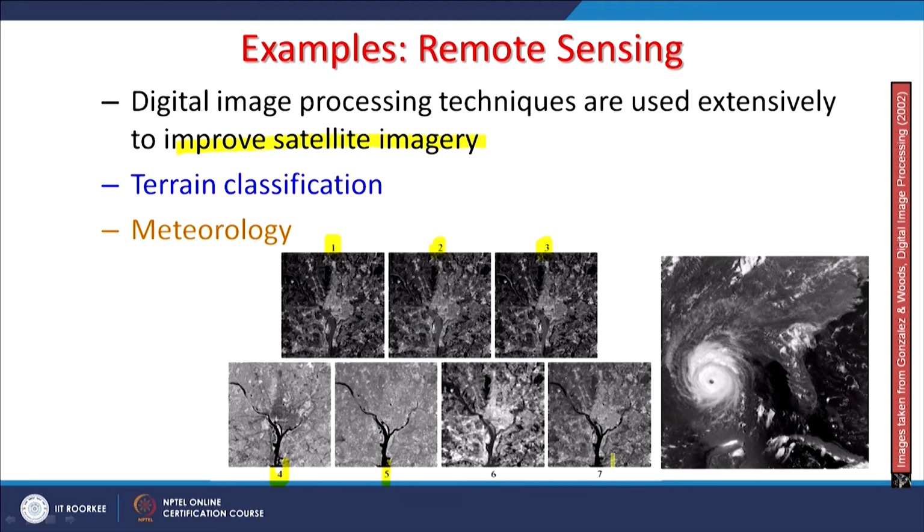So, different bands are giving images of different parts of the EMS spectrum. Now, the best technique, if you are working in multispectral or going for false color composites, which we have already discussed in previous lectures, is that individual bands should be first enhanced and then the combination should be made. That will really provide you a very significant quality change in the satellite images. So, that is another help to improve the images.